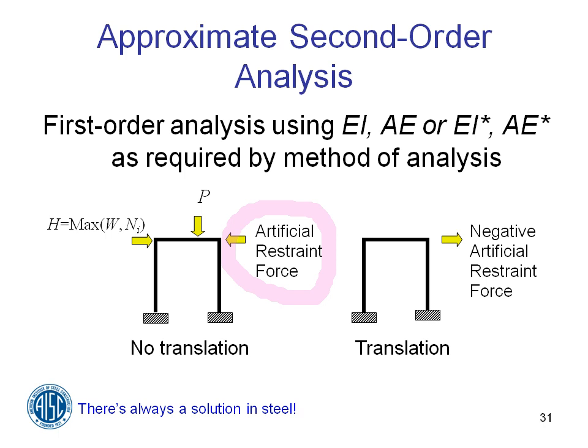So whatever we get as our forces in the members and our moments in the members, those are the NT, or no translation effect. But that force really isn't there, so we have to analyze the structure when we take that off. And when we take it off, we put that force on in the opposite direction. The structure sways sideways, and those are the results that we call the LT results, or the lateral translation results.